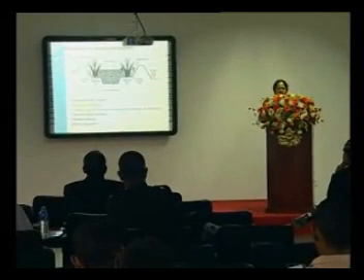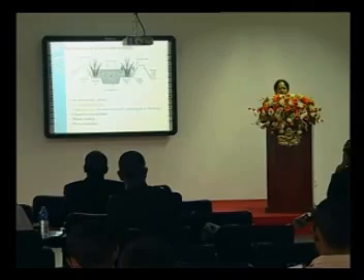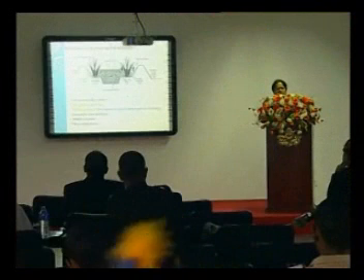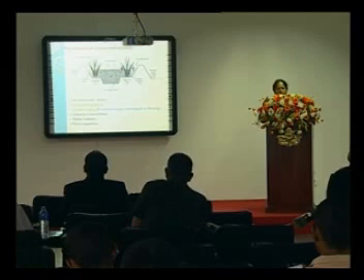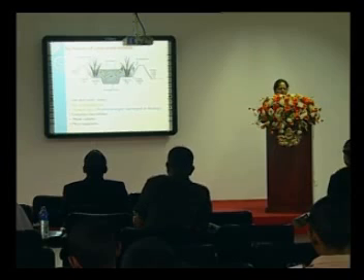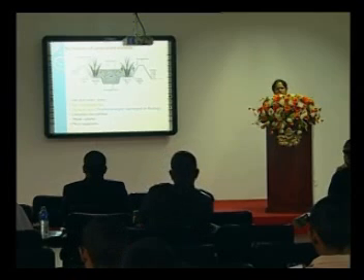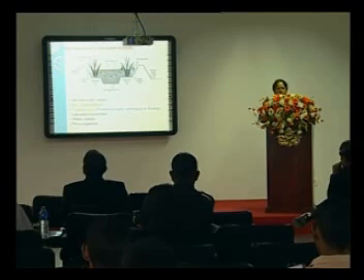If we see the key features of constructed wetlands, it should have a definite inlet zone and outlet zone for even distribution of wastewater and collecting it, and it should have bed media for interaction of pollutant removal, and wetland plants. These can be rooted, immersed, submerged or floating plants, and there should be a subsurface barrier to prevent wastewater leaching into the soil, and a water column and microorganisms. All these interact together to improve the water quality.